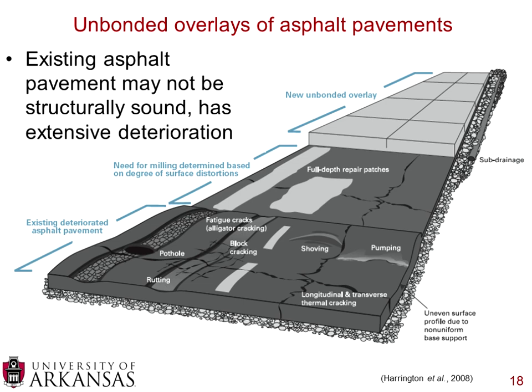When we're looking at asphalt concrete, again, not structurally sound. And what does that mean? Well, that means that some of that rutting can actually be going down into the surface layer or into the subbase or subgrade. You can see that there's some waving going on of the roadway, and that indicates that the roadway is not necessarily on a stable foundation, or the loads being applied to the roadway are going above and beyond what the design was for those roads. But very similar types of distresses, your potholes, your rutting, fatigue cracks, block cracking, and those types of things.